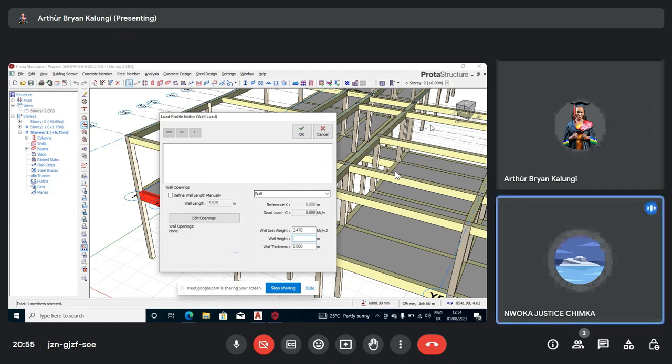Now, I am not telling you that the block wall will contain all the 3.0, because there is a roof beam above it. Can you see that? Roof beam having a depth of 300. So that block wall will stop where the beam bottom is, right? So we will now subtract 3 meter minus the beam depth of 300.